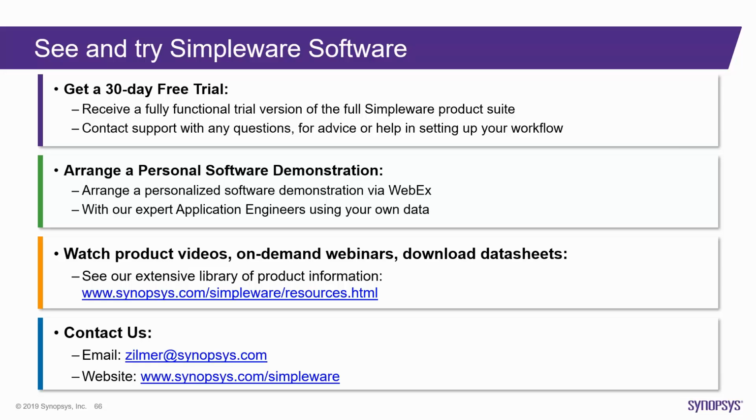And then Simpleware has all the inbuilt functionality on the tools available, where you can segment it. You can reconstruct a 3D model from the 2D images by stacking together in all X, Y, and Z directions. So it's a fully 3D reconstructed model, and while doing the reconstruction, you can individually, discretely segment different materials, different fibers based on the grayscale differences, which is a lot of efficient tools are available where you can differentiate those grayscales in the images itself, and you can model a 3D CAD model of the things.